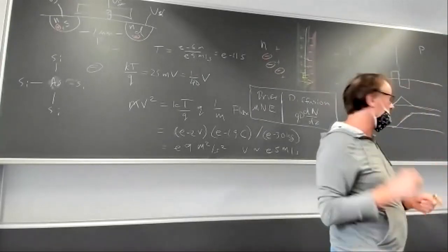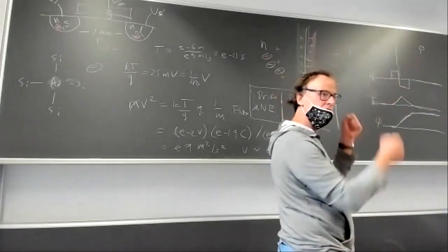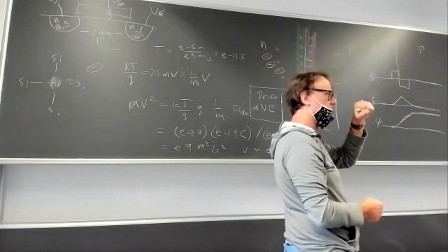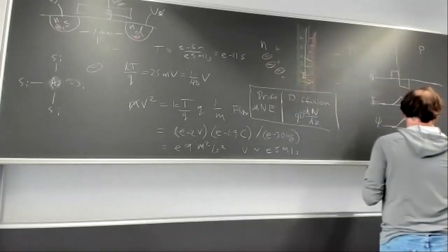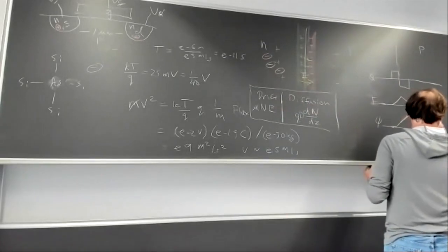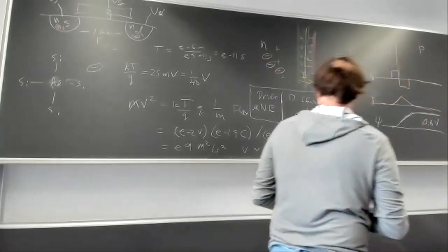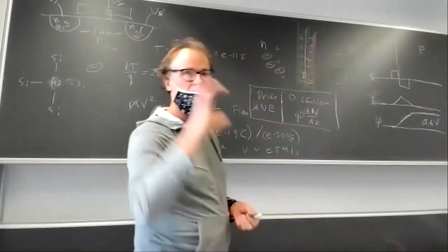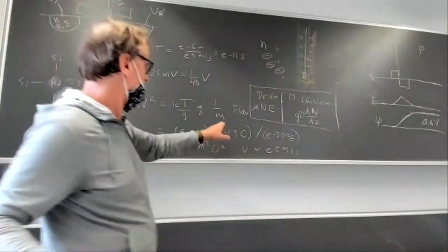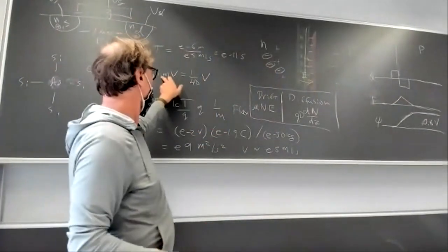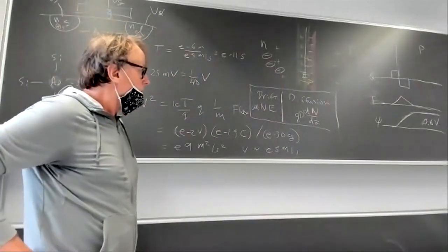Yeah, there's no hard rule. It depends on what the doping ratio is between the two sides. If you dope it really strong ratio, then the built-in potential will be higher. But typically it's around 0.6 volts or something. 0.6, 0.8 volts, something like that. Yeah, again, it's much bigger than the thermal voltage. Much bigger than kT over q. Okay. Hundreds of millivolts, not 25 millivolts.